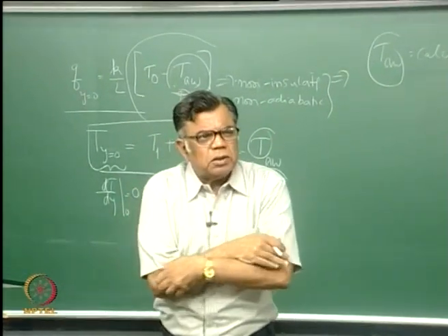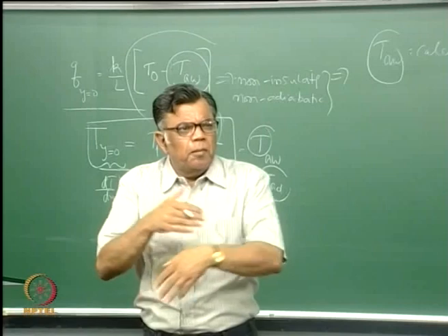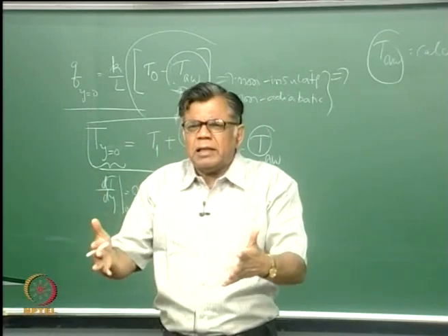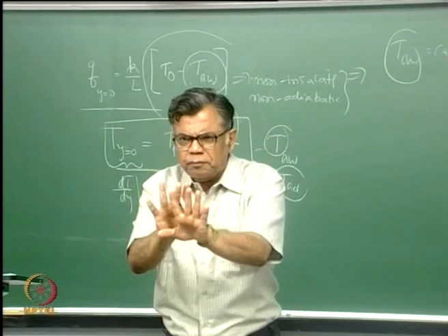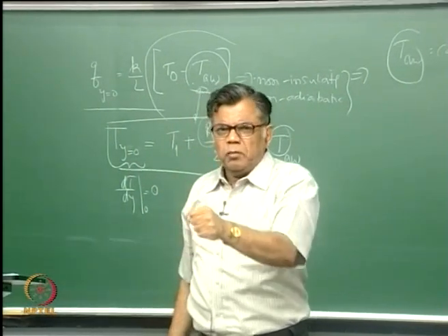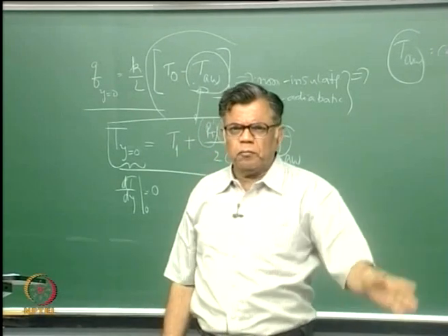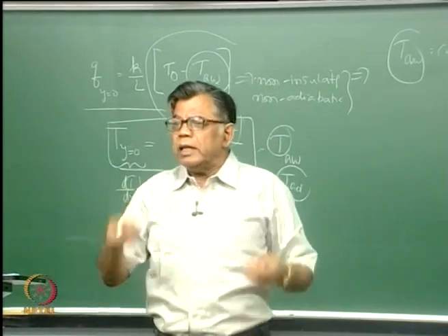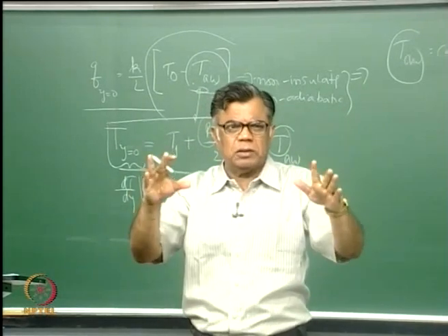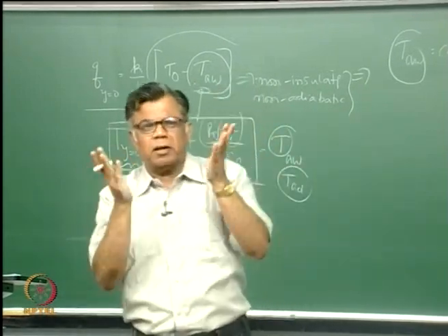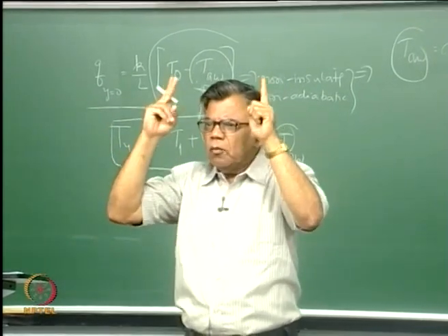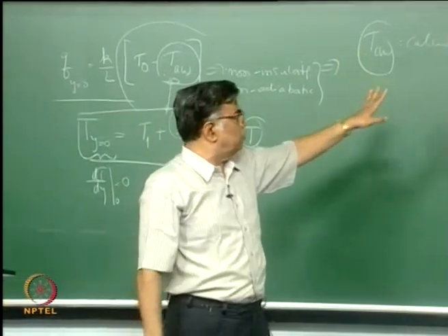That is the right temperature. The moment there is U1, U1 squared by 2 Cp is there. It may be small, large, very large, that is a different matter, but it is there. U1 is not 0. The moment U1 has come into the picture, whether it is a Couette flow or you go to the boundary layer flow, there is kinetic energy, there is viscosity, therefore there is viscous dissipation. The question is, how important is it? Now, when you do not know what it is, what you should do is take this expression for calculation.